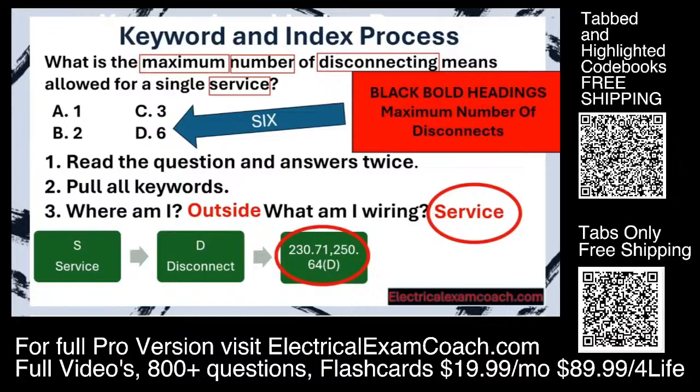the articles. Well, Article 230 is all about services, and Article 250 is all about grounding, which doesn't have anything to do with my question. So the obvious choice here would have been to go to Article 230. And this is really going to be helpful. In this case, they only have two, but sometimes they have three, four, or five possible codes that it could be in. And you're going to get faster and sharper. I know you can do it.